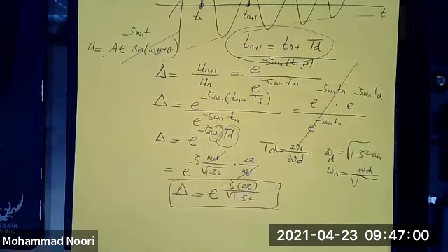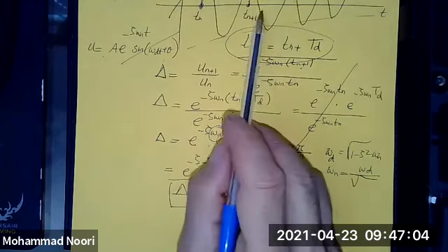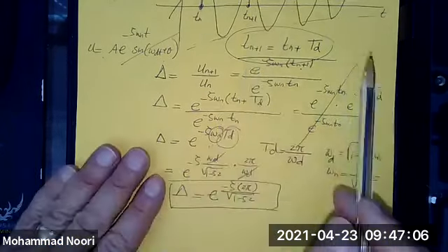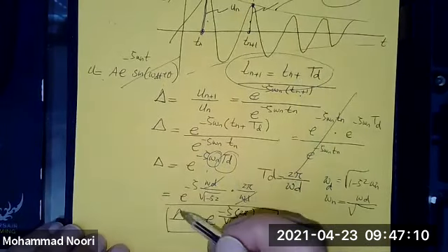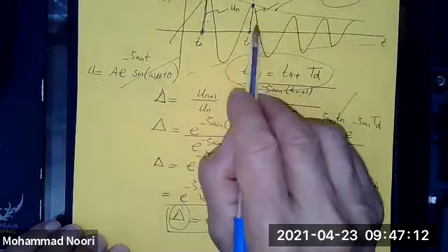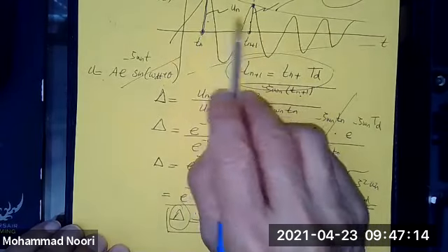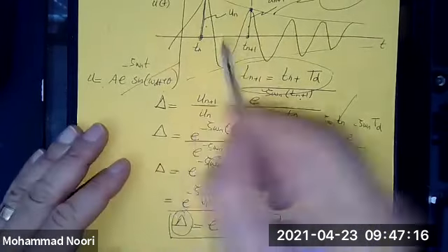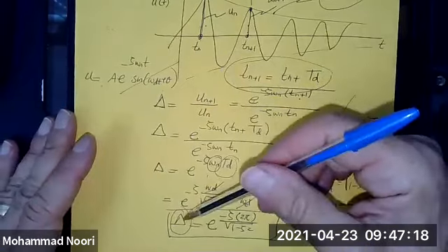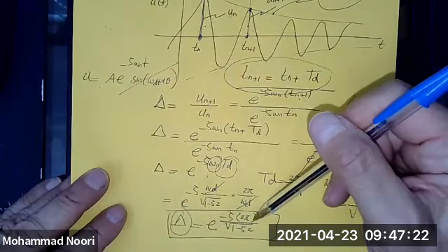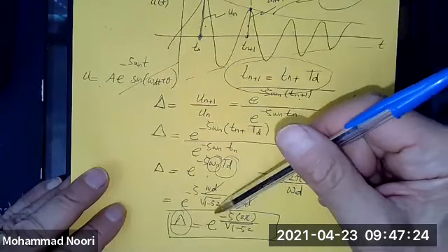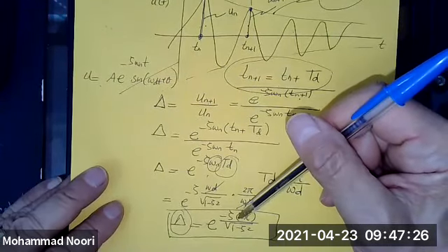Look at this relationship. Experimentally, when you're plotting this curve, let's say you can look at the oscilloscope and you plot this, right? You can measure this. You consider two successive peaks, divide those. That's what this is. The left-hand side is this exponential function in terms of zeta. So from that, you can find zeta.